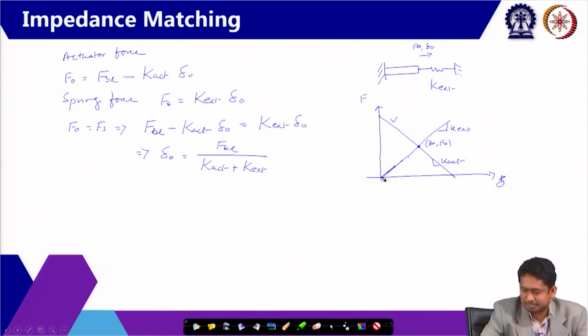Now, as the voltage increases, the force increases, and we keep on getting this area. So, the area under this triangle increases, it becomes maximum when we reach our desired voltage, and again from here we can come back and keep the cycle going on. So, in one half cycle when voltage goes from 0 to V, the amount of work done is the area of this triangle.